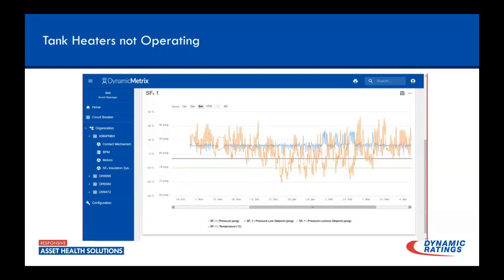or we're at least going to put enough pressure on the internals of those tanks that we're going to stress the gaskets and all the joints, to the point that now we've created a leak issue later on, when that breaker's in service, and that's going to be something we're always going to be addressing.